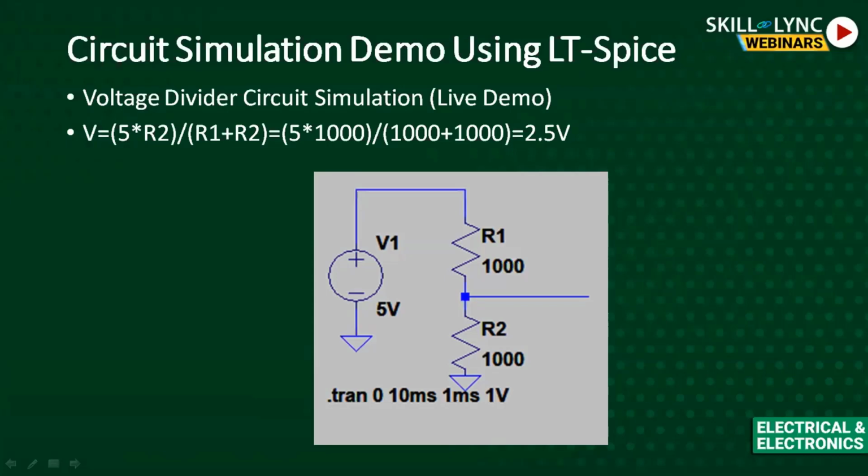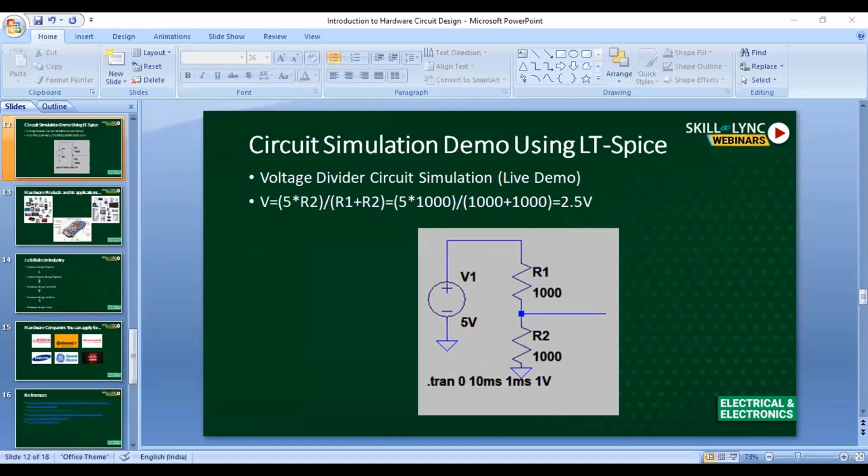So we just quickly take a look at the simulation tool, and here you can see the LT Spice window. Here you have options for different components. This is a ground component, then you have a label option where you can give labels to the nets, then you can select resistors, capacitors, inductors, and diodes. There is a library inside LT Spice, so you can select an LED, a MOSFET, or NPN transistors, whatever you're looking for. Based on the need we can select the components. You can select a TVS diode, varactors, and Schottky diodes.